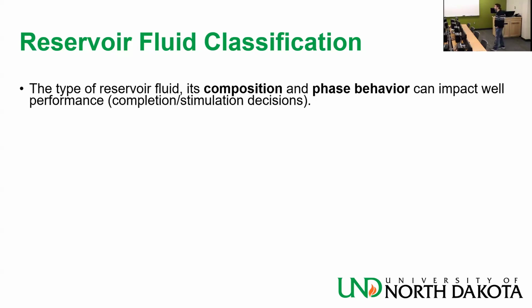The more CO2 and H2S the oil has, we call it sour. If it doesn't have, we call it sweet. Removing it, we call it sweetening. CO2 and H2S in particular, H2S, can mess up things tremendously. First of all, CO2, which is the more mild of the two, mixes with water, makes something called carbonic acid, and starts destroying your equipment, basically.